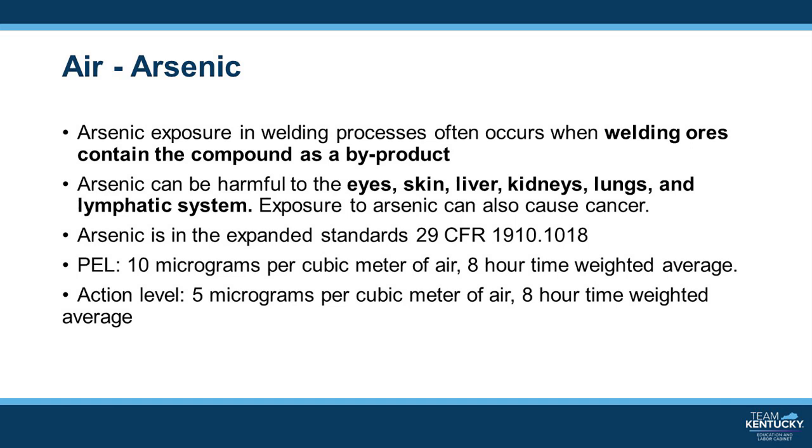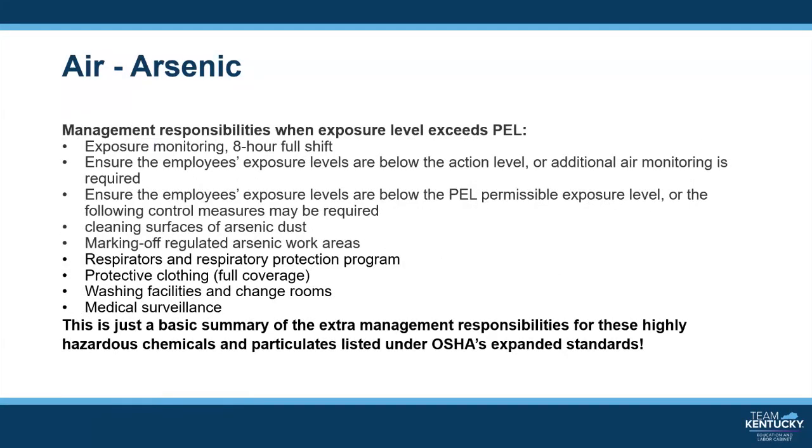The regulations on arsenic are in the expanded standards under 29 CFR 1910.1018. The PEL for arsenic is 10 micrograms per cubic meter of air over an 8-hour time-weighted average. The action level is 5 micrograms per cubic meter of air. Again, since arsenic is in the expanded standards, management has extra responsibilities when the exposure level exceeds the PEL. It would require exposure monitoring for an 8-hour full shift workday.